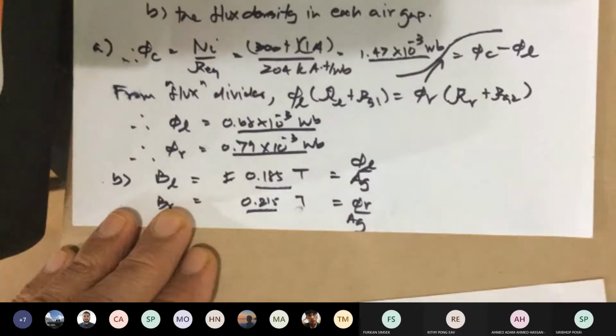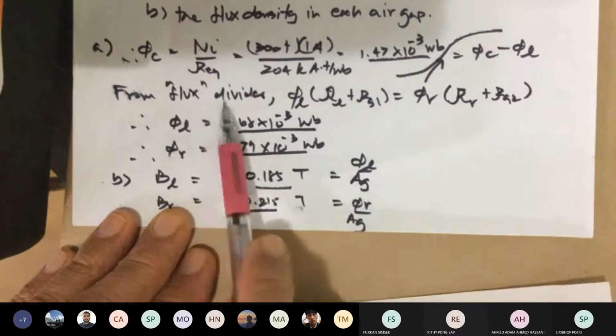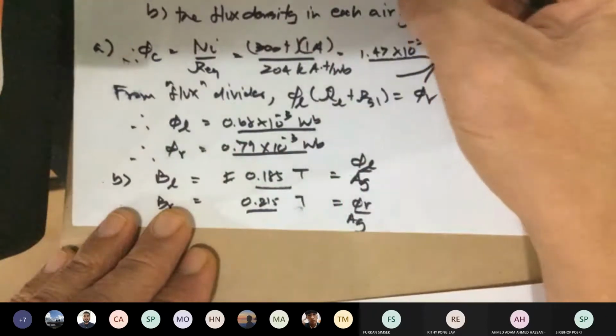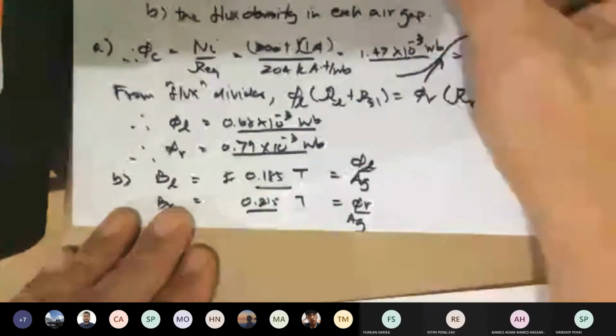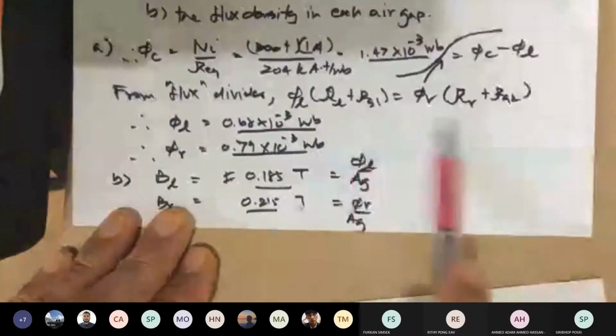That's why we make use of the magnetic circuit, imitate the equivalent circuit, because the flux would be acting like a current in a regular circuit. And the voltage, the magnetomotive force on each branch would be like a voltage on the electric circuit. See, that's how we can do that.